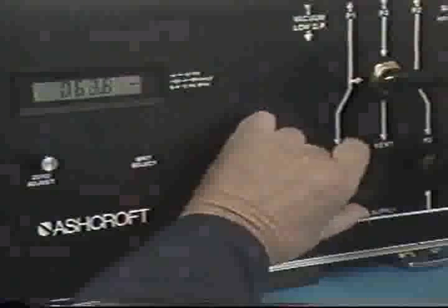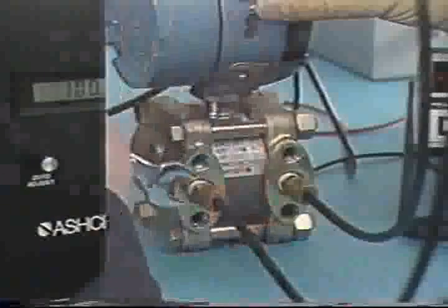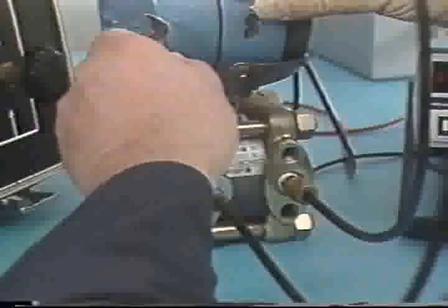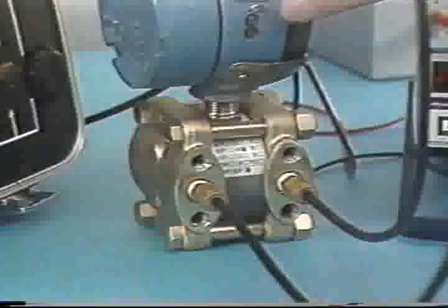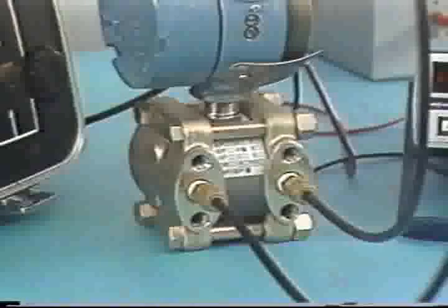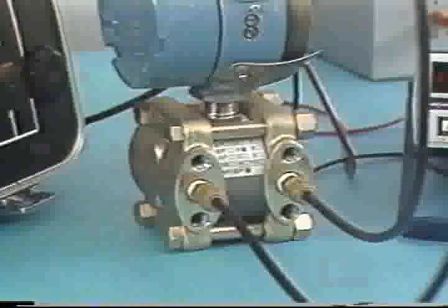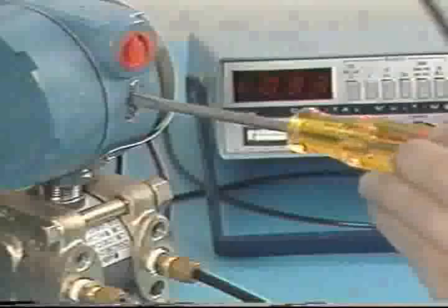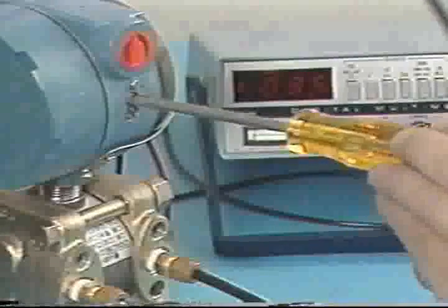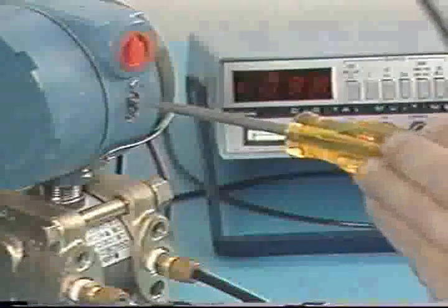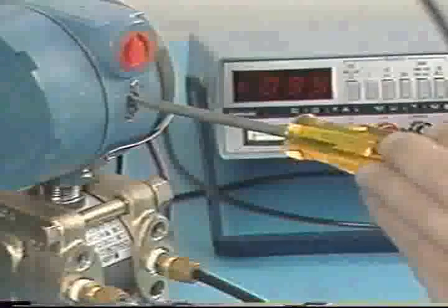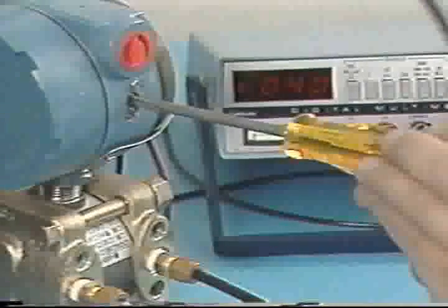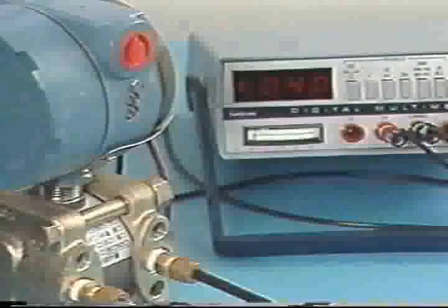When calibrating a differential pressure transmitter for a wet leg application, it's good practice to apply the hydrostatic pressure of the liquid in the wet leg to the low side of the transmitter. In this procedure, connect the low-pressure calibrator to both ports of the transmitter. A regulator is used to add the hydrostatic pressure of the wet leg to the low side. Then, zero the output until 4 milliamps of output is produced. In some cases, the zero screw may not provide enough adjustment. In this event, you'll suppress the zero value with the zero suppression adjustment.